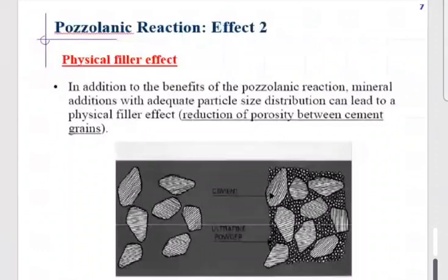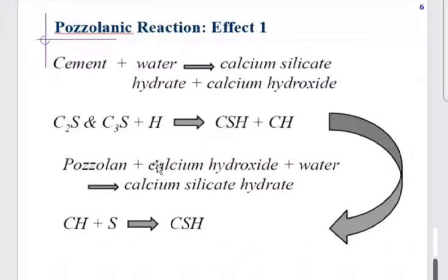So now talking about enhancing the durability, if we can reduce the porosity at micro or nano level, cement particles are interlinked, their voids are there. So these voids can be filled with the ultrafine fillers. This is one physical characteristic. कि हम physically voids को fill कर दें, तो हमारे पास voids नहीं होंगे, porosity reduce हो जाएगी, तो we can enhance the characteristics of the concrete.